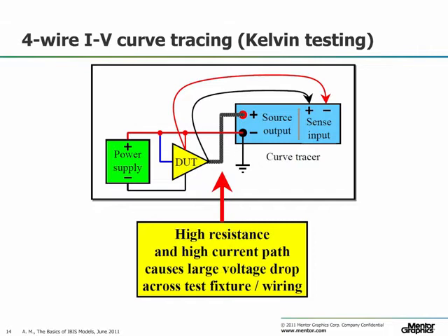If you can't reduce the resistivity of your fixturing to a negligible level, and if you cannot make use of the sensing input of the curve tracer to compensate for these effects, you might want to consider numerical compensations to eliminate these losses from your measurements. In order to perform such numerical corrections on your data, you would just have to replace the device under test in the fixture with a short and repeat the IV curve measurement with that short in place of the device.